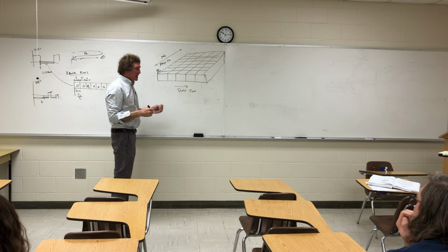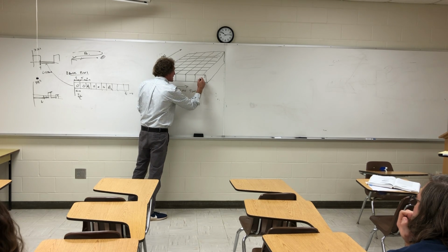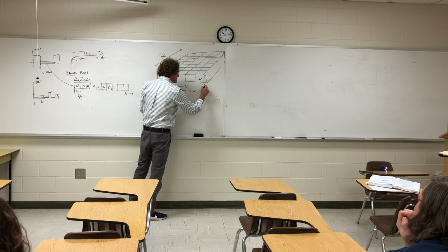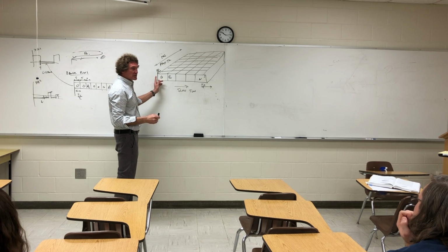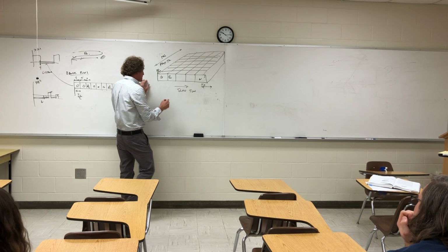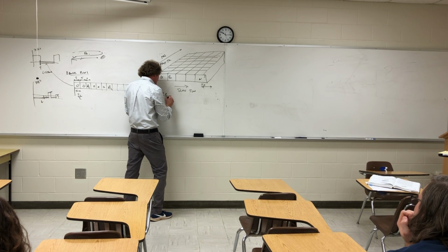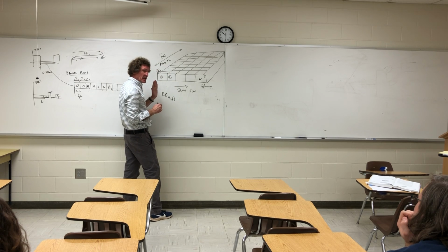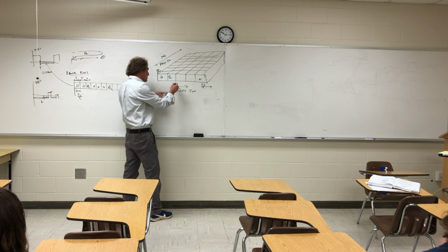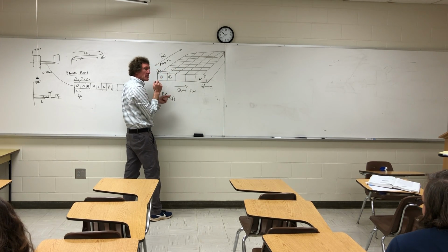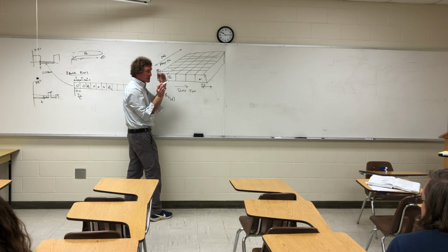Follow me on this? Now, think about this. Here's pulse 1, 2, all the way till we have pulse N, where this is now a dwell time. That's only looking at one point. So normally what you have is, you see I have a 2 by 2 here, right? So I'm gonna have a vector for range bin, RB, and it's gonna be indexed, call it IJ. So now I can say for any IJ, I might be the fast time, J would be the slow time, right? You can say for maybe the third pulse, a target appeared, but it didn't appear here, so we can get into the probabilistic of how likely is there a target there. You follow me? It's still looking at only one point.